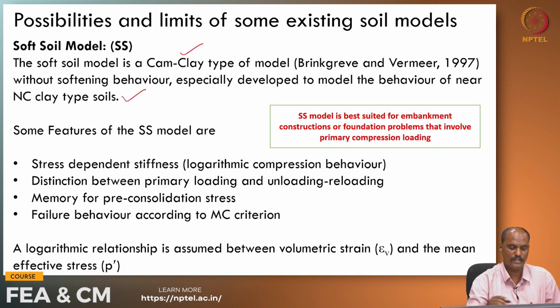Which is similar to modified Cam clay, and there are some special features attached to this soft soil model, which are the stress dependent stiffness or the logarithmic compression behavior, distinction between primary loading, unloading and reloading, the memory for pre-consolidation stress Pc, and the failure behavior according to Mohr-Coulomb criterion. So these are all the special features when compared to that of the modified Cam clay model.